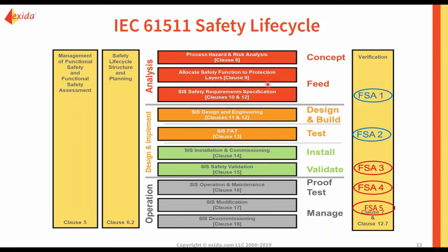So it covers that analysis phase, but then also going through design and implementation, so looking at the actual design of the safety systems, the factory acceptance testing, installation and commissioning, all the way through validation. So making sure that not only you've really understood the concepts, that you've developed the right systems, but that you've built, tested, and installed them correctly.